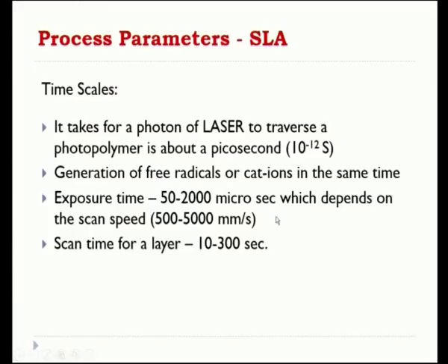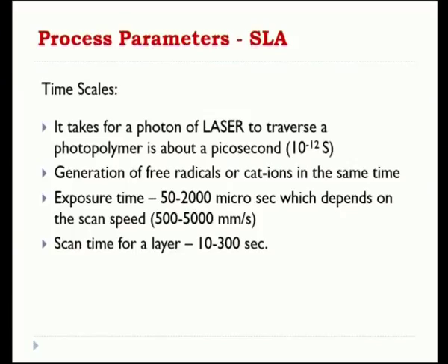How effective we should be in exposing a laser, we should be very cautious, because not everything is going to take place in seconds, right? Even the exposure time, you can see it is only in microseconds. Again, you can see the scanning speed is in millimeters per second, right? That also uses a very minimal time period. So for the total process, the layer build-up time is not more than 10 seconds. That depends upon the material length again, but the maximum at the moment is only 300 seconds for laying up a single layer.